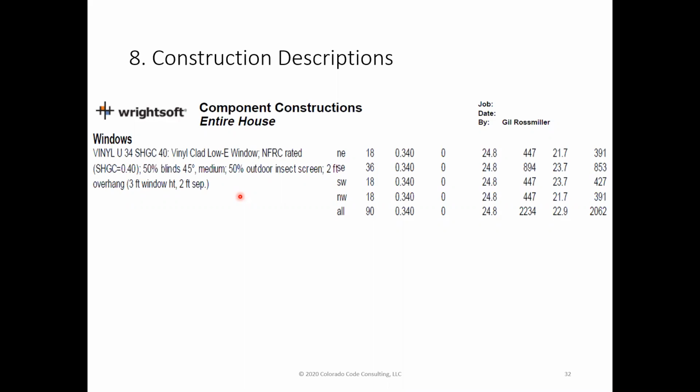There are times when, let's say it's the west facing window and you don't have any shades on it, that room will have an excursion you could not believe. I've had rooms that have required a ton of air conditioning just because of the windows, and only during a certain part of the day. The code doesn't talk about that, but designers should be aware of it, and I'll show you where that shows up. So no requirements for overhangs, but if you've got them, you need to take advantage of them, and same thing with blinds and shades.